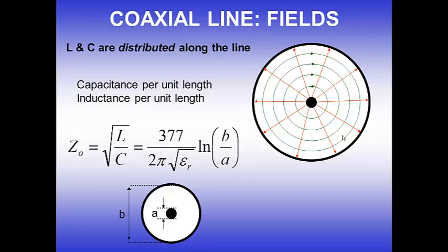So in the case of a coaxial cable, it's very well known that you have to talk about a capacitance per unit length. So when you're using coaxial cables at lower frequencies to make measurements, you have to be careful about how that capacitance might load your circuit. Often, therefore, you use things like oscilloscope probes at lower frequencies.